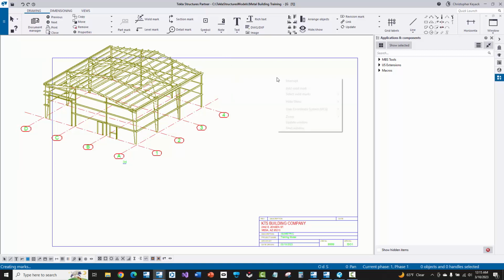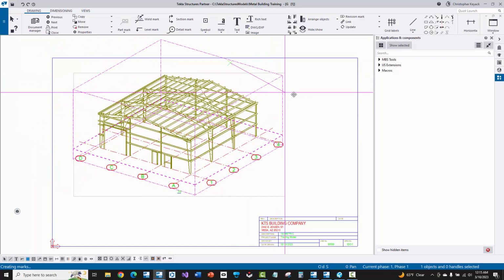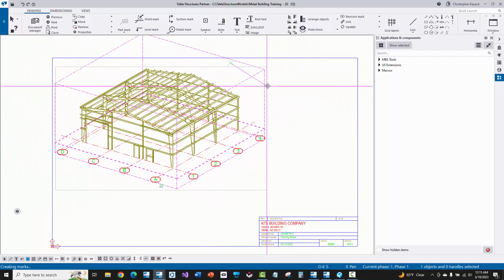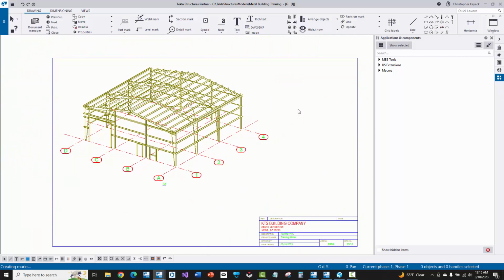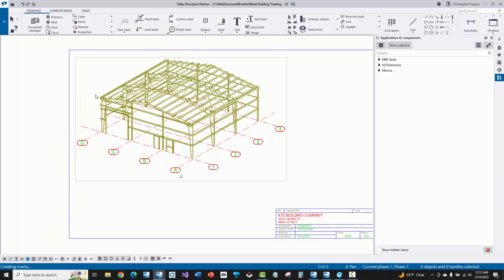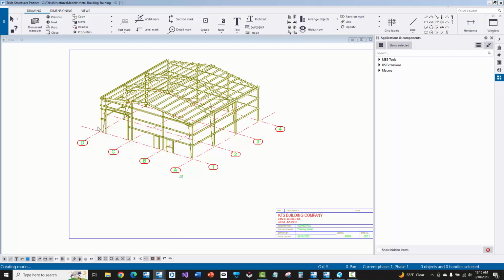Now I can right click, if I just click on the background of the drawing. Okay, for some reason the Arrange Drawing Views isn't showing up there, but if I just select the view and drag it with my mouse after I select it, it'll move the view to the location that I want. And there we go, we have our first drawing done, and I can just go ahead and close this down. I'm going to mark this drawing as ready for issuing because I've reviewed it and it looks good.